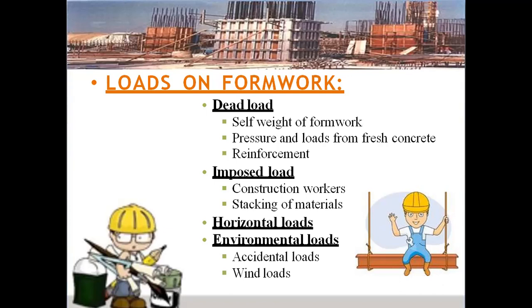And the imposed load, like construction workers, the labor weight, the stacking of materials, the materials we use on the slab like vibrators, lifting materials, the pouring of concrete and the distribution of the concrete to certain parts, and the horizontal loads like environmental loads, accidental loads, and also wind loads.